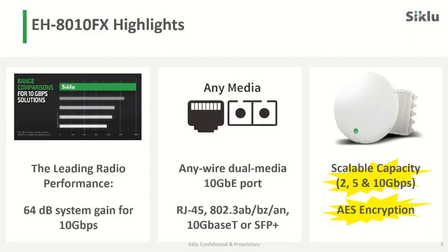If you are choosing a specific location, you can say 1, 2 kilometers or more, and basically you will get the capacity and the availability of the link for the distance that you want to operate. So a good planning rule is 2 kilometers with the 1-foot antenna and almost 3 kilometers with the 2-foot antennas.